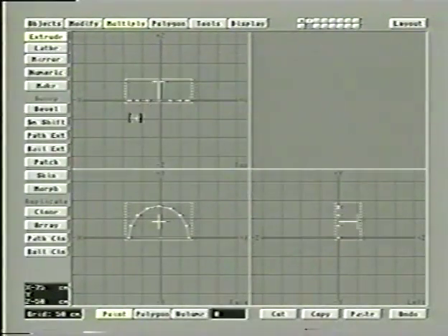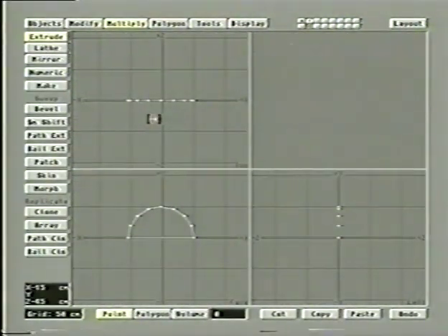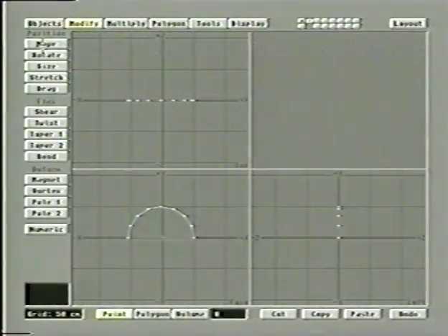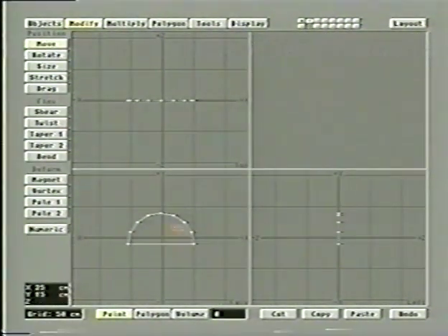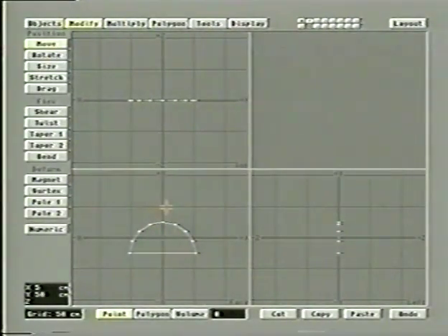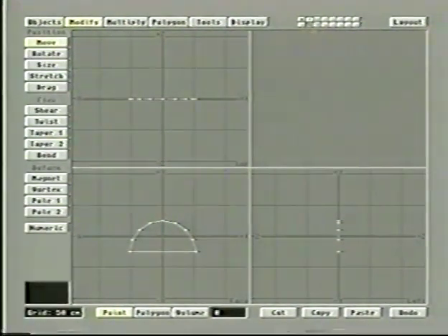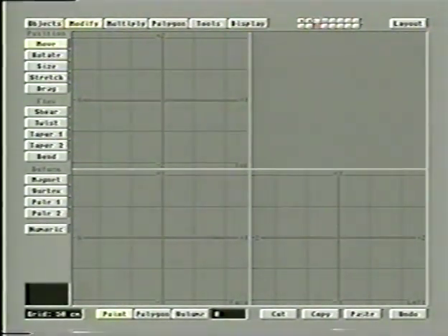Now, of course, you could draw it anyway, but as you can see, sketch mode is a quick, easy way to draw shapes like this. So here's what we're going to do. Let's undo what we did there on this shape. So we'll bring it back to 2 dimensions. What we want to do here, let's actually move this down a little bit so it's more centered. Quick way is the F1 key, or I could move it manually, but F1's quicker. So this is centered up. And what we're going to do is let's go to layer 3, make that our active layer. And this is where we're going to draw our sketch path.